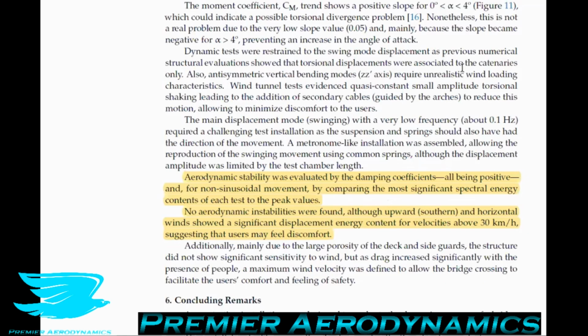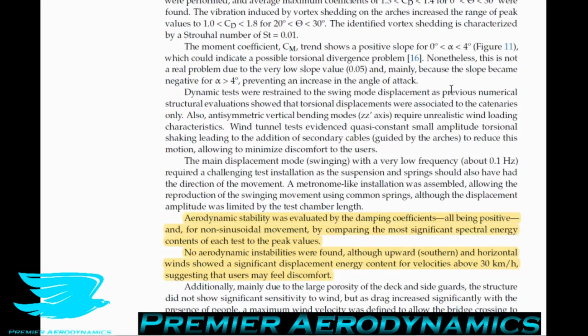So, in conclusion, the aerodynamic instability was evaluated by the damping coefficients all being positive, which is good, and for non-sinusoidal movement by comparing the most significant spectral energy contents of each test to the peak values. No aerodynamic instabilities were found, although upward and horizontal winds showed a significant displacement energy content for velocities above 30 km per hour, suggesting that the users may feel uncomfortable.